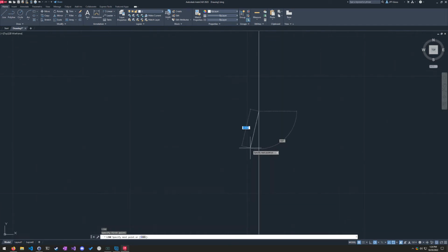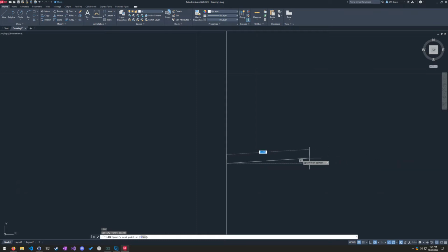Well, I want that other end of the line to be horizontal. And I want it to be half of the distance from where the border was to the edge of the paper. And that's where we're going to get half of 3/4, which I had said before was 3/8. And that in decimal form is 0.375. Now, notice that when I pull this line to be horizontal, it snaps on a green line.